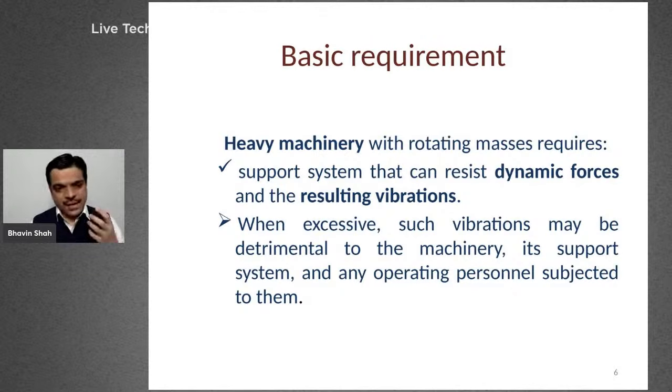The machine could be damaged because of the excessive vibration, and even the entire support system of the machine could be damaged. Also, if there are any operating personnel working around the machines, they could be affected by the vibration. That's why the vibration has to be limited within the permissible limit whenever we are designing machine foundations for heavy equipment.